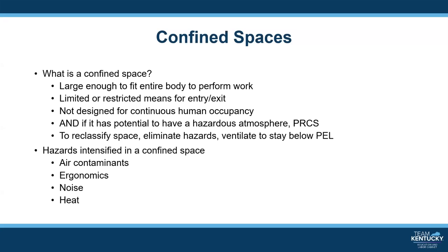which would make it a PRCS, which is a permit required confined space. You can reclassify a space so that it's not a PRCS if you eliminate the hazards and you ventilate so that you stay below the PEL.